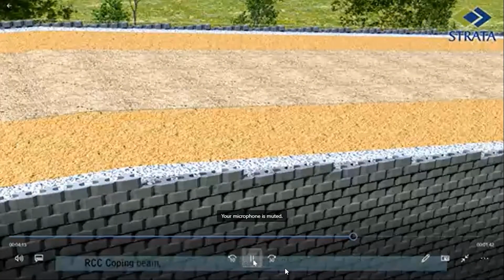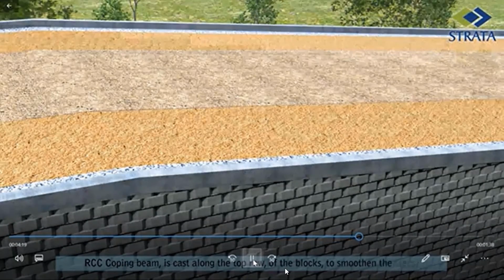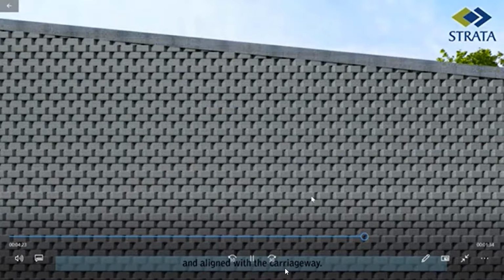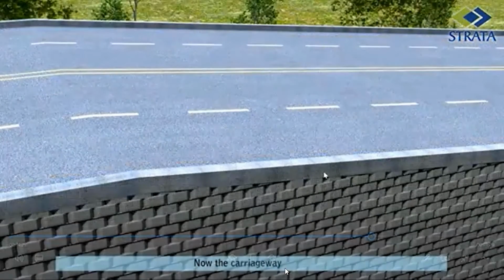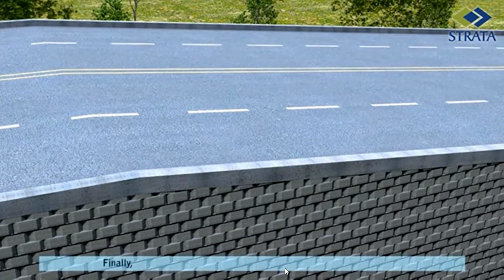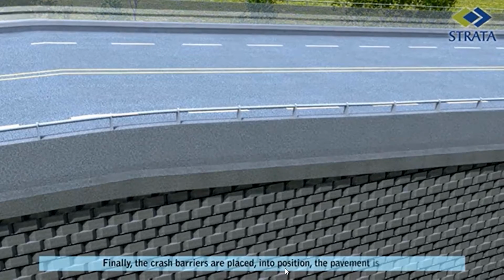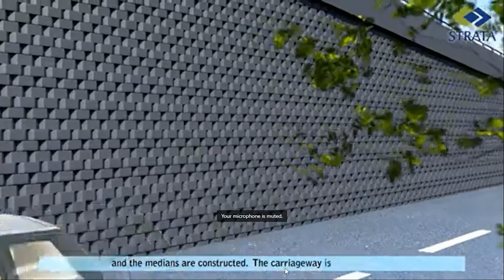RCC coping beam is cast along the top row of the blocks to smoothen the steps and align with the carriageway. Now the carriageway is laid. Finally, the crash barriers are placed into position, the pavement is laid, and the medians are constructed. The carriageway is now complete.